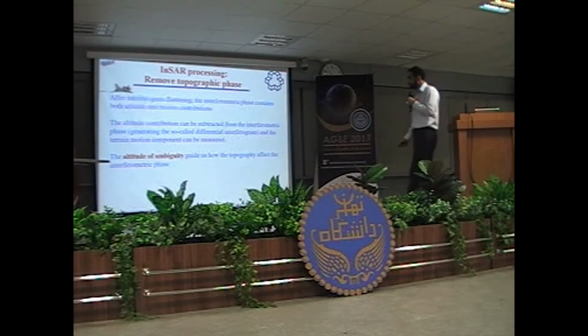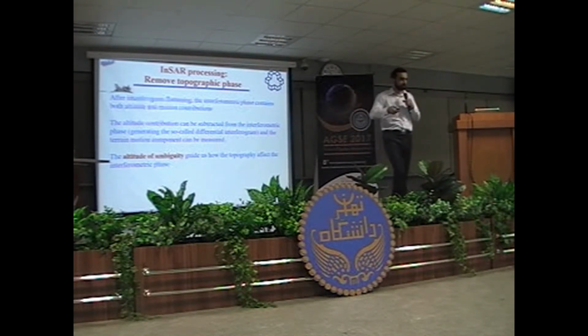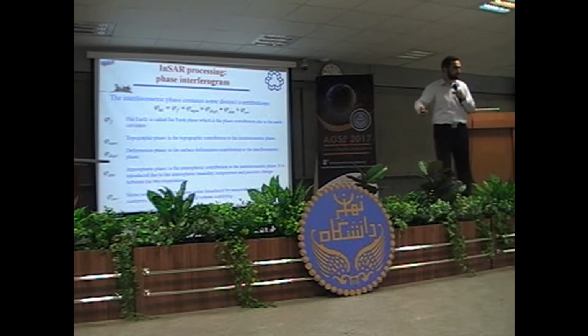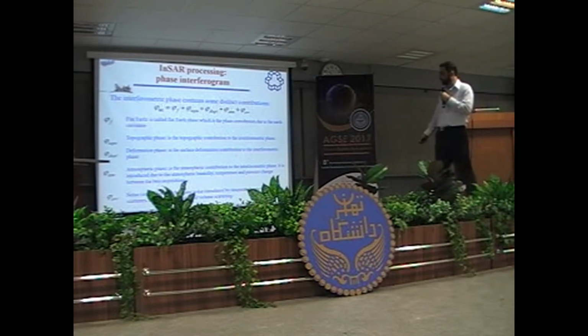So the second part is to remove the topography phase from the original one. This was our equation. We already removed the flat earth. If the purpose is displacement, now we have to remove the topography, because topography has a very big amount of contribution over the interferometric phase.